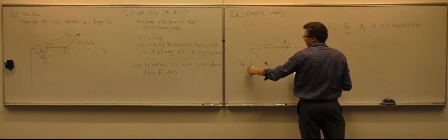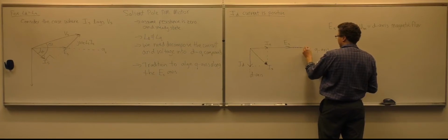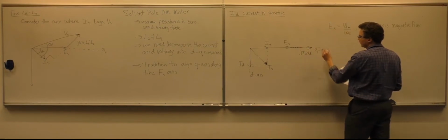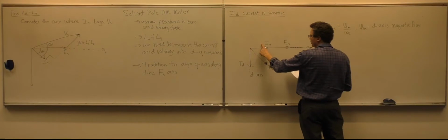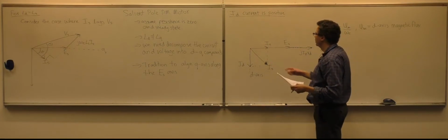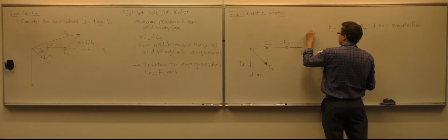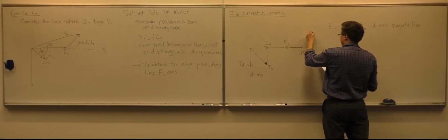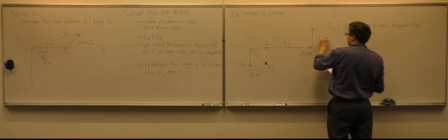So that will rotate this vector by 90 degrees, and so we'll have a component along here, which is J ID XD, and then we have IQ, and when we multiply that by J omega LQ, that's going to rotate that by 90 degrees, and so we'll have another vector component coming up like this, J IQ XQ.